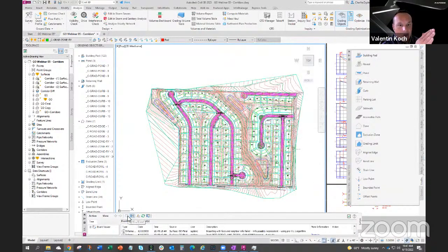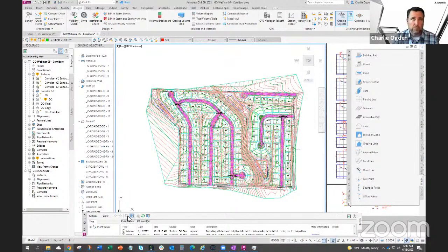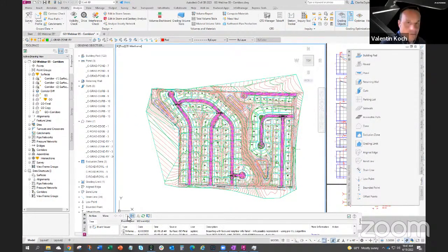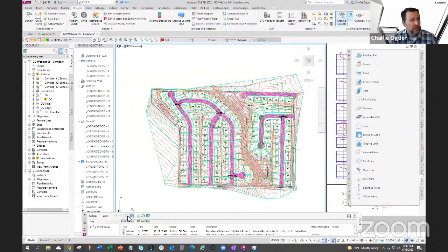And if, for example, you have a maximum slope constraint somewhere, it will just create this walkout automatically. But you'll want to actually go in and define the reveal so that you have the right elevation difference. Yeah, you can use the reveal feature we showed earlier, probably in the second webcast, to get the actual elevation difference you want.